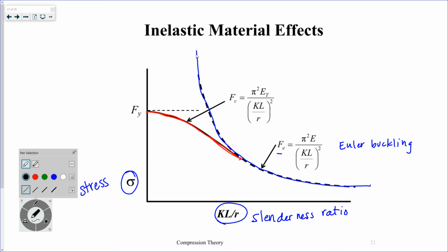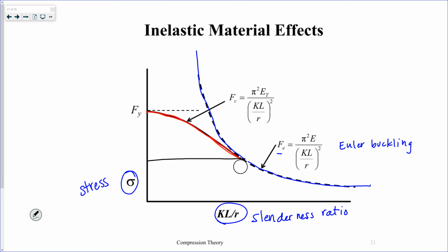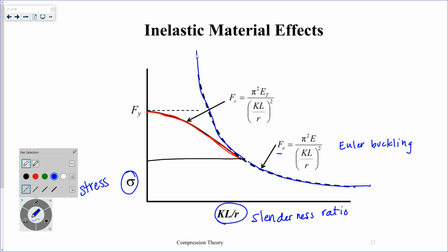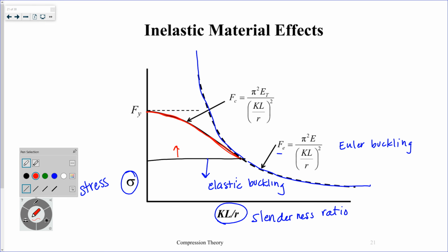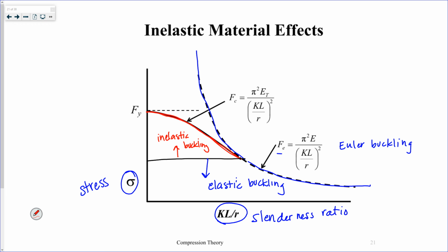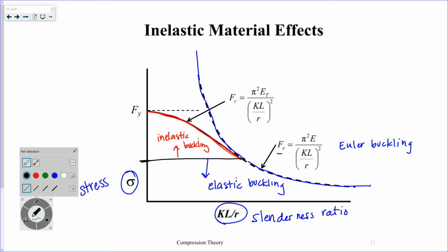I can break this up by the stresses below this point are associated with elastic buckling, and above this point, and this point right here is Fy minus your residual stresses.